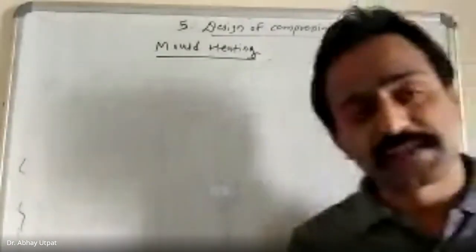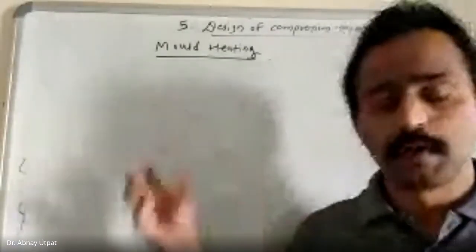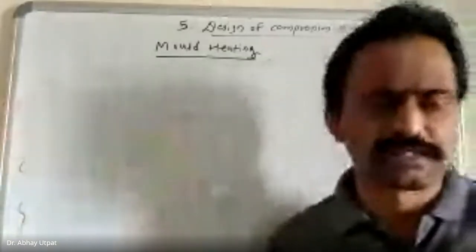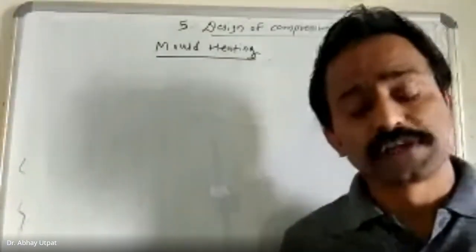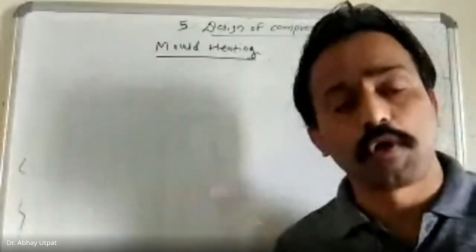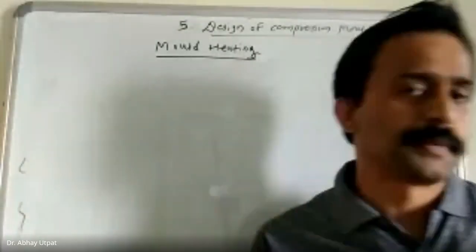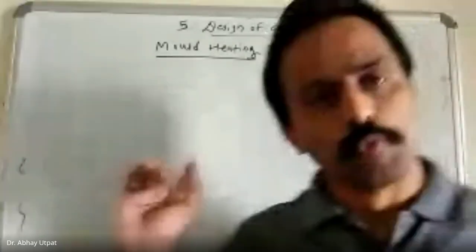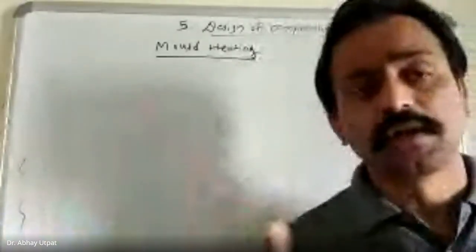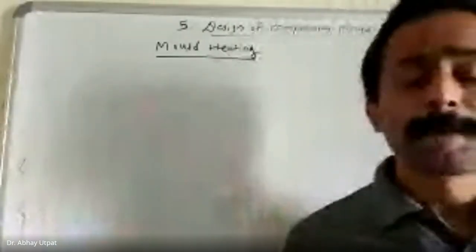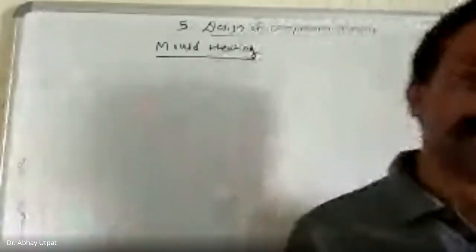So what temperature is required for heating of the mold? A certain temperature is required, and that temperature is maintained. How to check whether the temperature is correct or wrong? Then some thermocouples are fitted in the mold. Now by circulating oil or steam, the molds are heated.